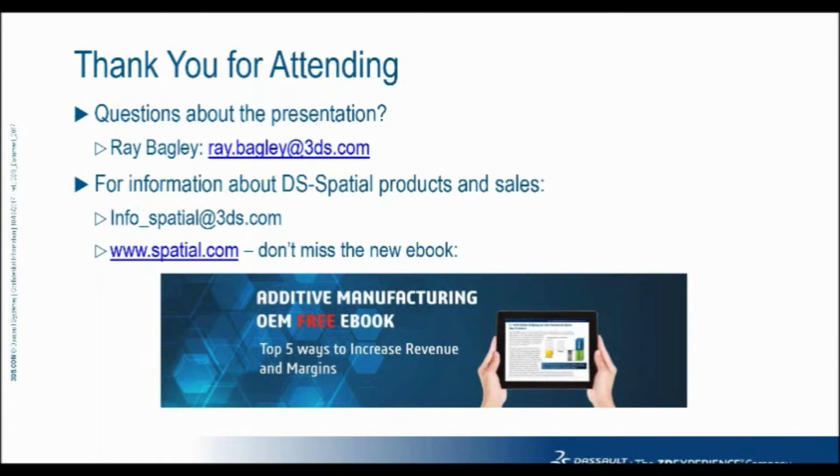As I said, I've worked with some 3D printer manufacturers working on what they consider a new and innovative printing technology that are working at such a fine resolution that they didn't feel they could accept the approximation error created by tessellating the part. And so they're building their paths directly off the very precise spline data from the CAD